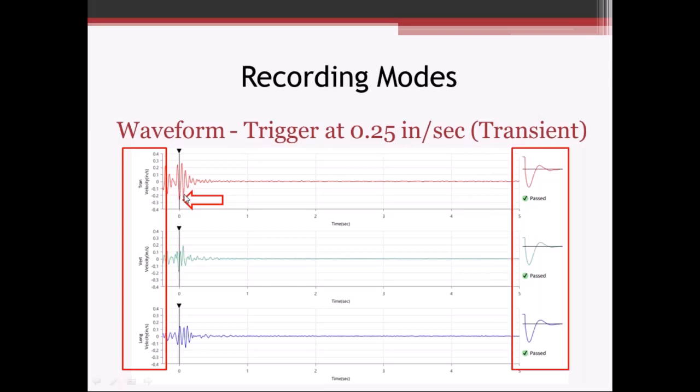And then one of the other things that we look at in this waveform data is, after this 5 seconds is done recording, it does a self-check on the geophone in each of these 3 directions: the transverse, vertical, and longitudinal. And essentially what this does is induce a voltage on the geophone and then release that voltage.